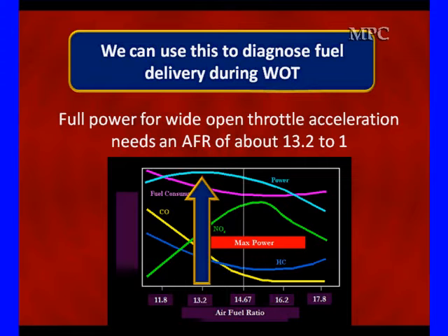Some people may say, why are you getting to the diagnostics so early? We want you to understand what we can do with it, to show you the value of the time it's going to take to learn how it operates. Now we can actually measure. If we have a fuel delivery problem, it will not be able to hold a full 13.2 enrichment. It will creep back toward 14. So this is a clear-cut diagnostic we've never had available to us before.